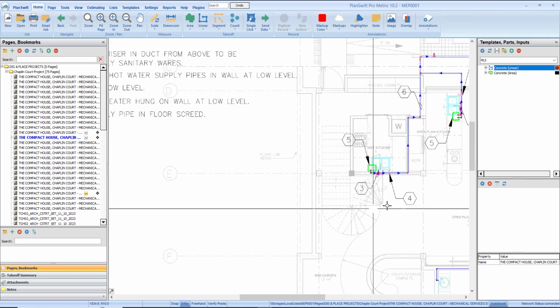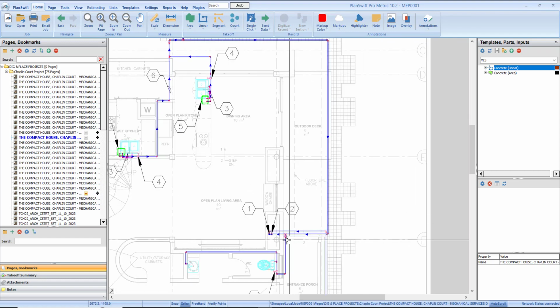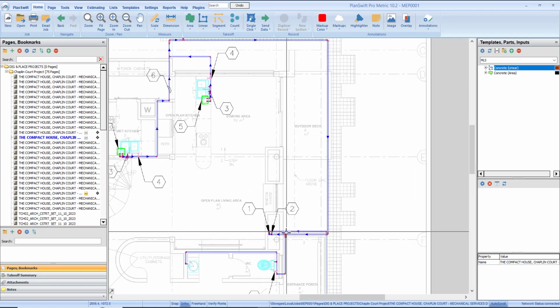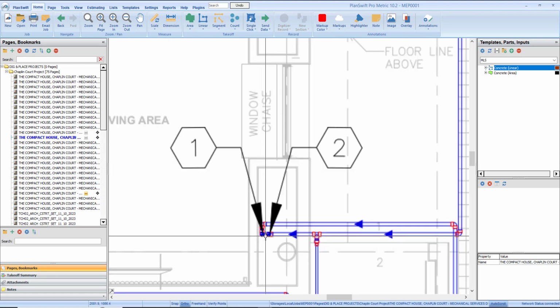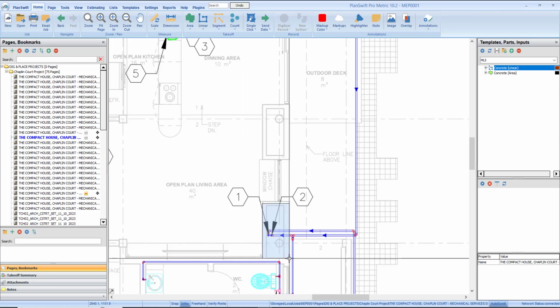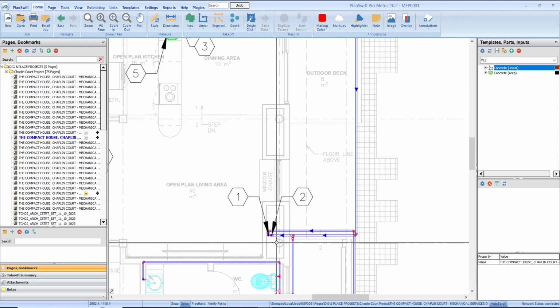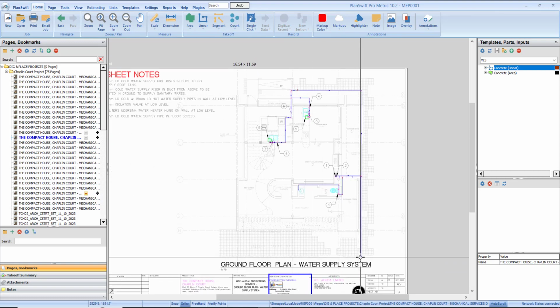Basically, the 32 mm diameter pipe serves as the ones that supply the 20 mm diameter pipe, and majorly they are the ones that are on this dot. So they are the riser pipes supplying the different floors. You can see the pipe we saw on the previous drawing, that is the pipe on the site plan for the water supply system.